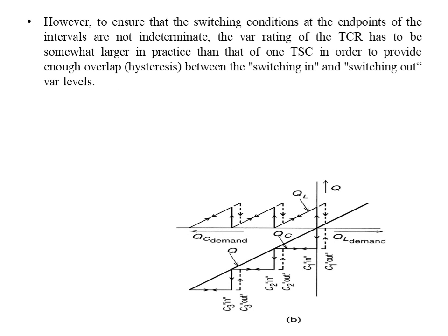However, to ensure that the switching conditions at the end of the intervals are not indeterminate, the VAR rating of the TCR has to be somewhat larger in practice than that of the TSC, in order to provide enough overlap between switching in and switching out VAR levels.